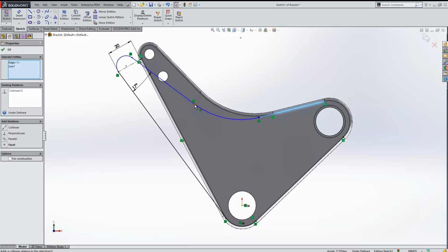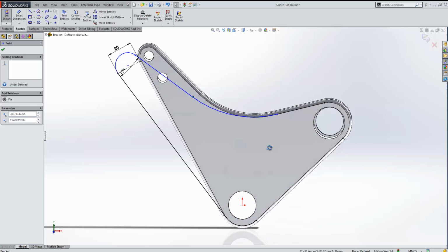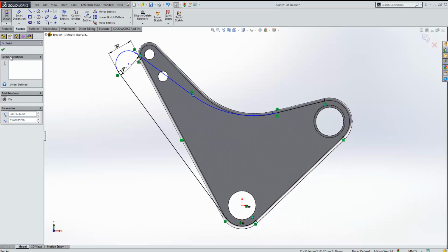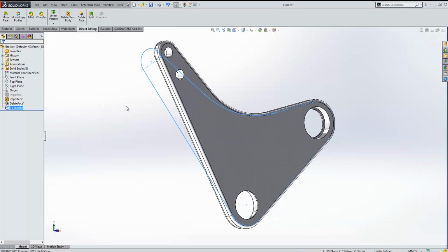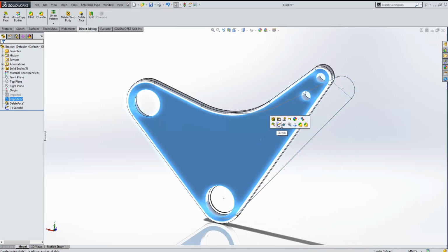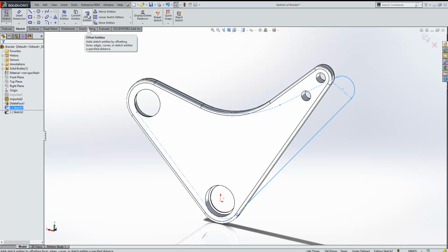And then we'll just adjust that so that it looks about right, so about there-ish. So this is where we're going to be moving it around. And what we're going to be doing is using this sketch in order to stretch this face to that new position. Now I'm also going to create a matching sketch on the reverse face. The reason for that is it enables me to control both the back face and the front face at the same time.